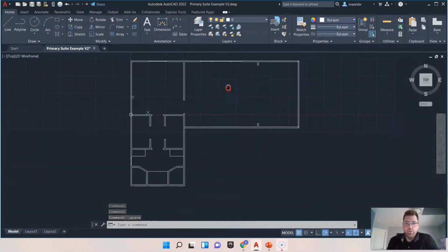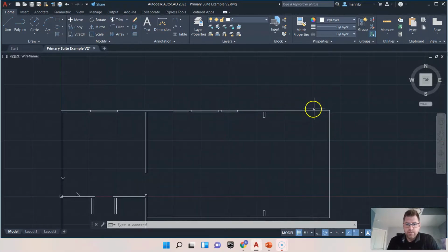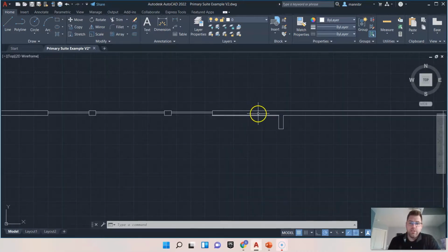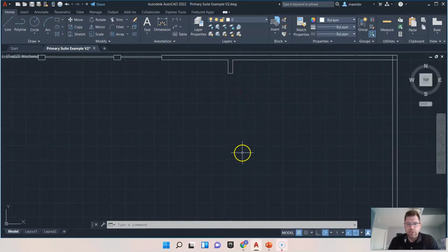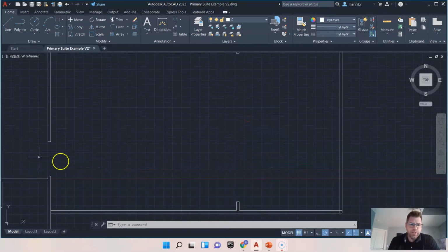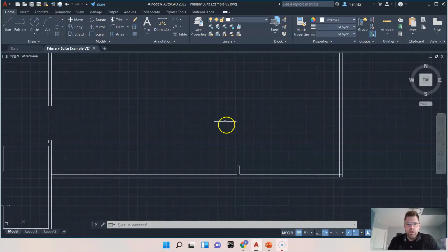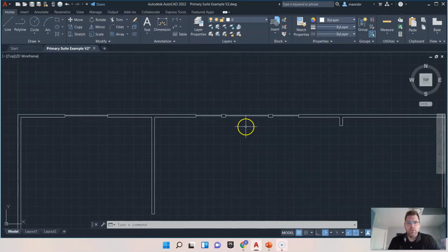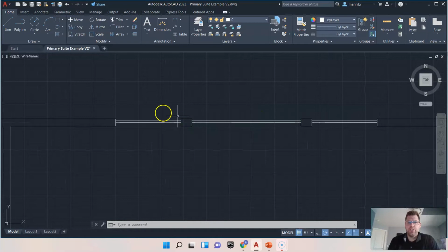So those are the basic things that I'd like you to be able to do to start. We ran some single lines, made a couple rooms, so I'd like you to do all of your rooms single lines. We set the thickness of the walls. We did some wall bucks or some openings, some large opening cuts, and that can be for a door, double doors. We did that over here on this side. Basically the same format. You put some offsets off the wall and then you clean it up. And then we did some window cuts. Usually we found our midpoint, or if you have specific spots, you'll have to run an offset to get to that line. And then we divided it and created each edge, cut them out.